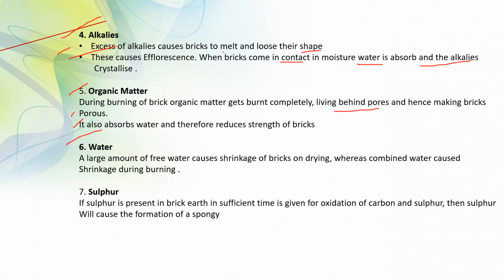Next, water. What is the most important parameter of bricks? A large amount of free water causes shrinkage of bricks on drying, whereas combined water causes shrinkage during burning. Last, sulfur. If sulfur is present in bricks earth and sufficient time is not given for oxidation of carbon and sulfur, then sulfur will cause the formation of spongy bricks.